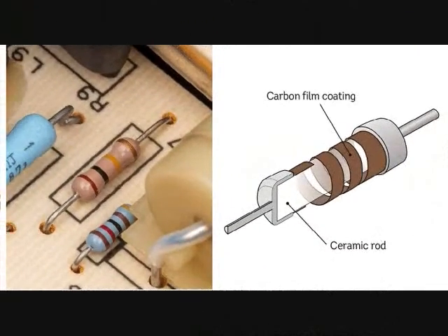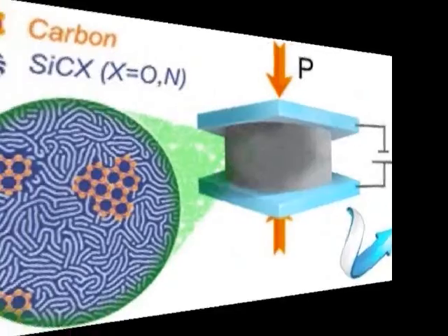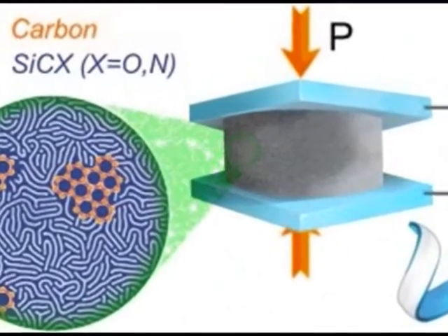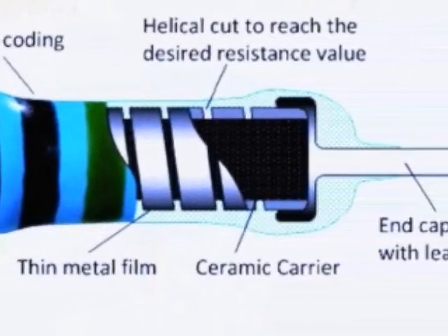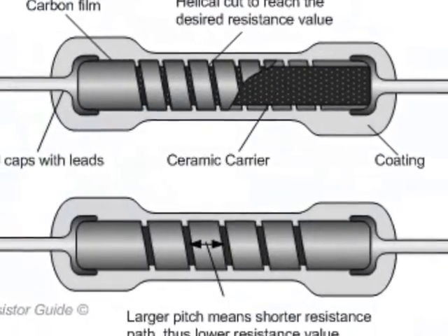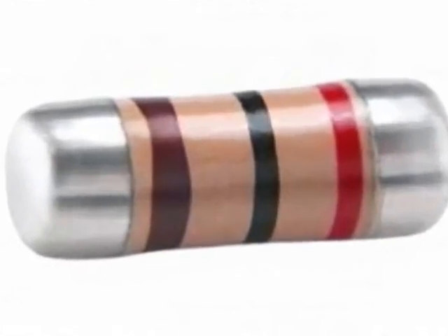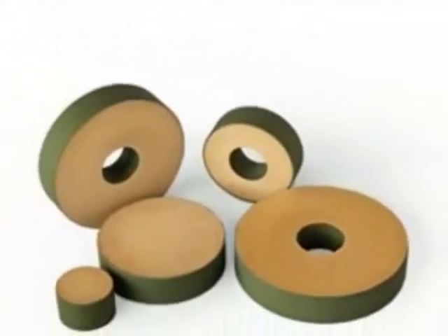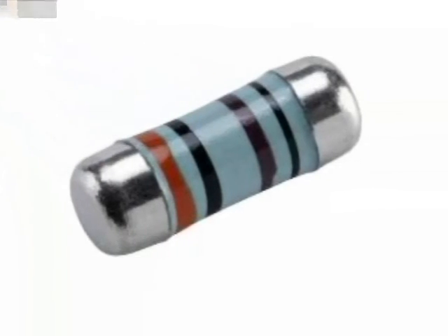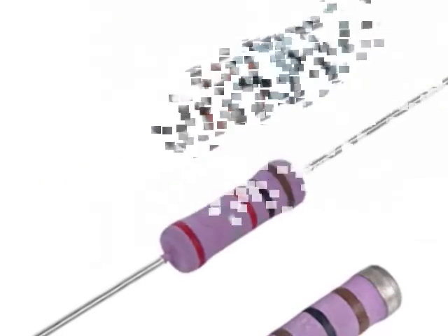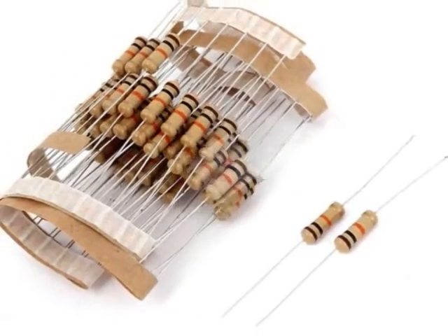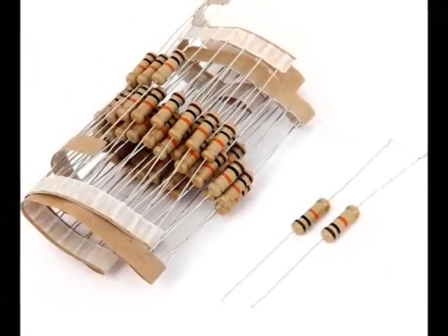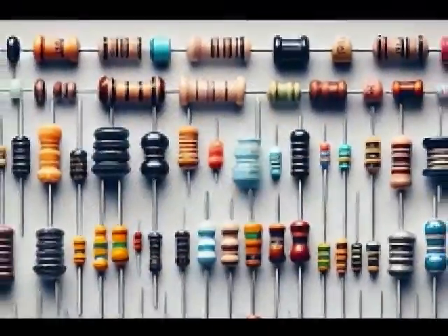The ratio of carbon to ceramic, conductor to insulator, indicates the amount of resistance. The higher the carbon content, the lower the resistance. Finally, this mixture is formed into a cylinder. The two ends of the resistor are connected to two cap-shaped conductive pieces with a base, which form the base of the piece. With these bases, the part can be soldered on the board. Finally, it is covered with insulation and resistance coating, and then color codes are inserted on it.